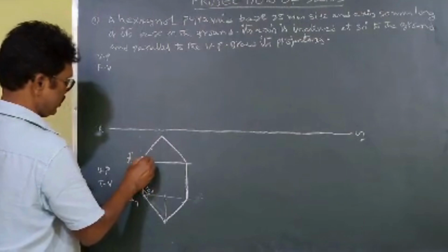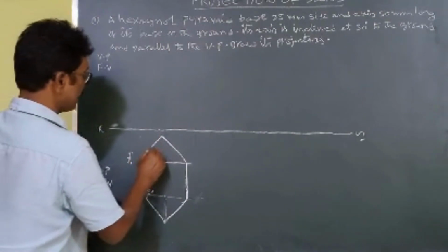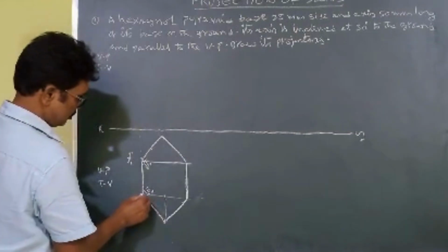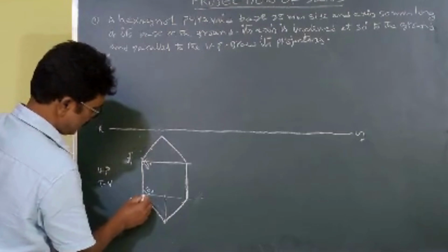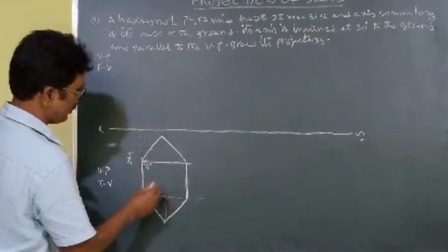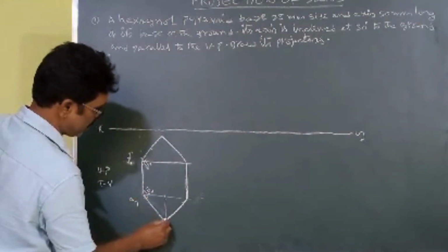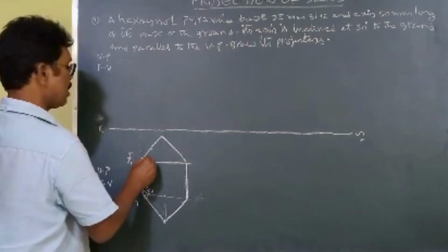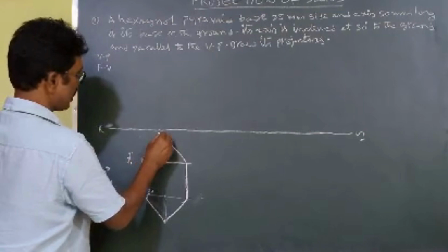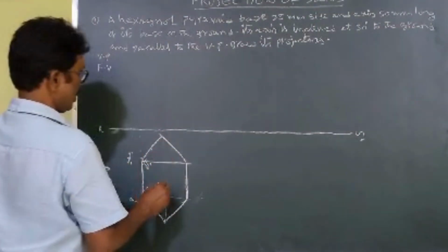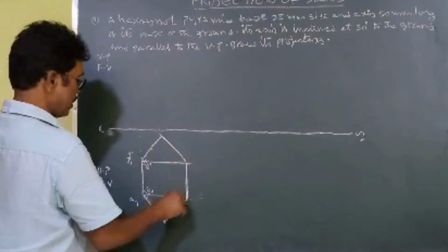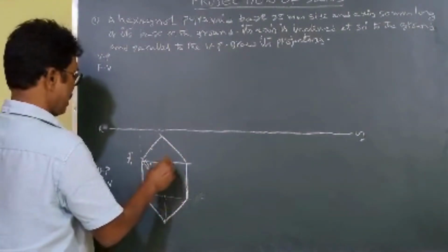At the same time, with F1 as center, 120 degrees, you draw a line. With A1 as center and 25 mm as radius, you cut it here. With F1 as center, the same 25 mm radius, you cut it here. Automatically they are on the same line. Without setting up any degrees, we can construct the rest of the hexagon.